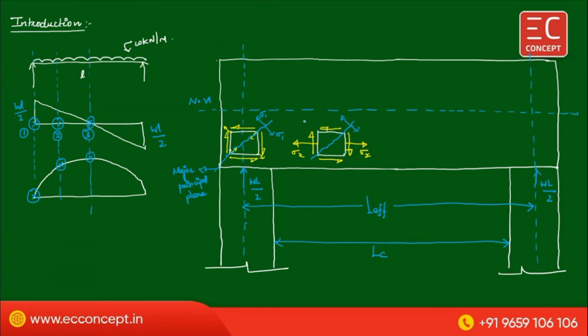This edge gets elongated in this direction, and this edge gets elongated in this direction. Therefore the tensile force acting along this diagonal, because of the effect of Poisson's ratio, will be contracted. So this diagonal is subjected to compression, and this edge is subjected to tension. Therefore the failure happens along this diagonal, and this also is a principal plane.